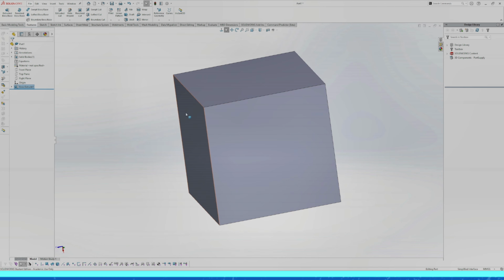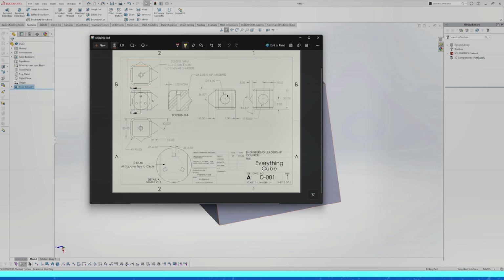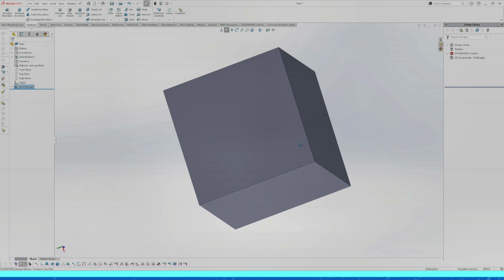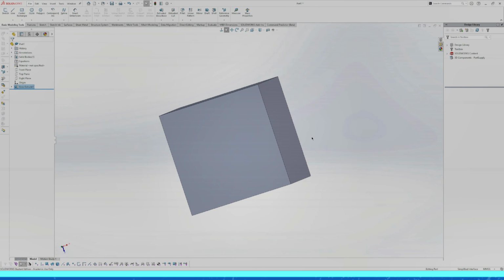All right, now that we have our 3D object, the next feature that I'm going to do is the corner radii. So you'll notice on this, there are small little radii on the corners, and they're not sharp. So we want to make those nice and smooth. To do that, we need to first figure out, if you turn this a bunch, we have no idea what up is. So you can go up to this button up here. These are all your view tools. So these will give you pan, rotate, if you don't want to use the mouse controls.